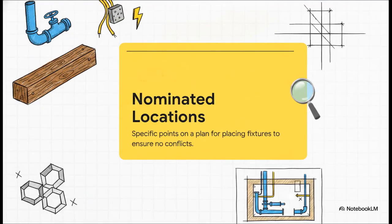So the crucial point is how all these strict rules come together into what we call nominated locations. These are specific, predetermined coordinates on a plan. And let me be clear, they are not suggestions. They are exact mathematical calculations designed so the plumber's pipes, the sparky's wires, and the carpenter's beams all fit into the same tight space without clashing. If you ignore nominated locations, you're going to have a very bad time.